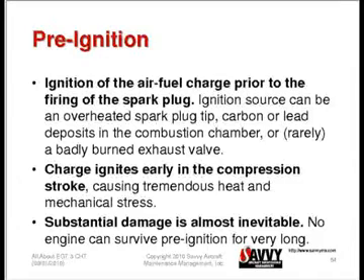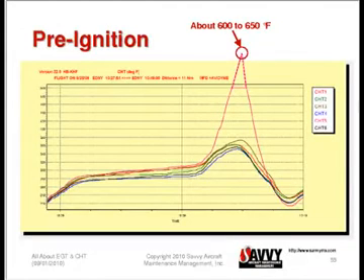Pre-ignition is much more serious and much more damaging than detonation. It causes enormous heat and stress on the engine, because effectively the peak pressure is occurring before the piston reaches top dead center, and it's actually trying to push the crankshaft in the opposite direction of rotation. No power assembly can survive pre-ignition for more than just a few seconds. It just puts enormous stress on the components, and so it has to be avoided at all costs.